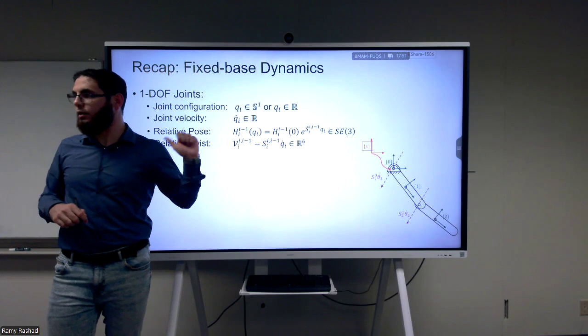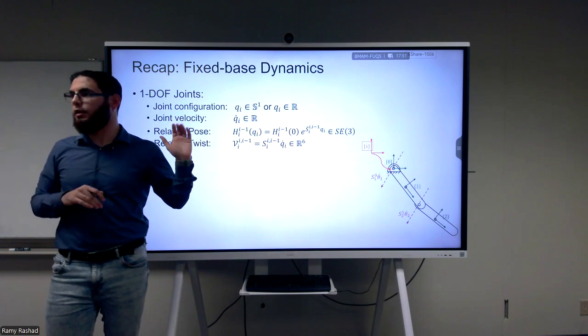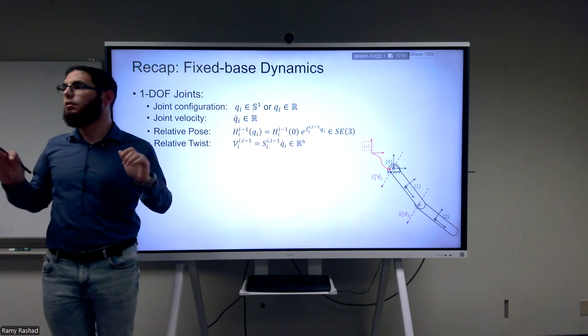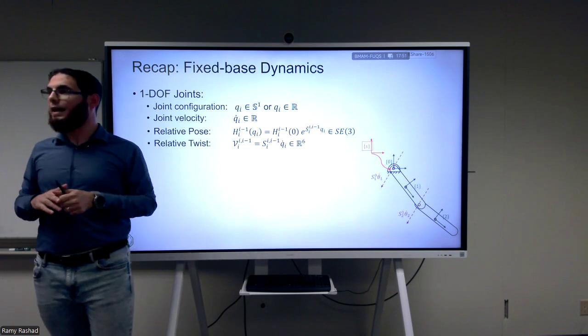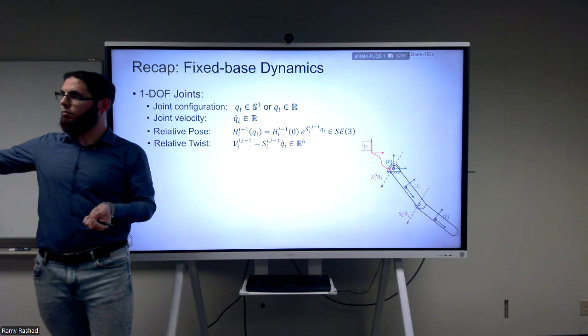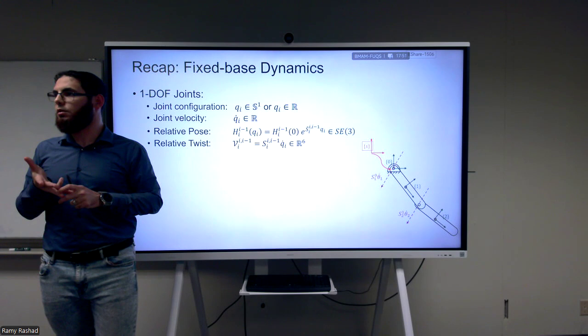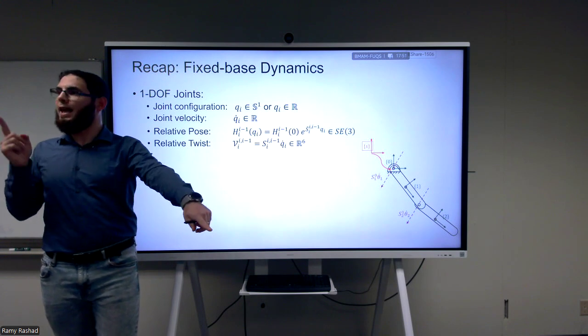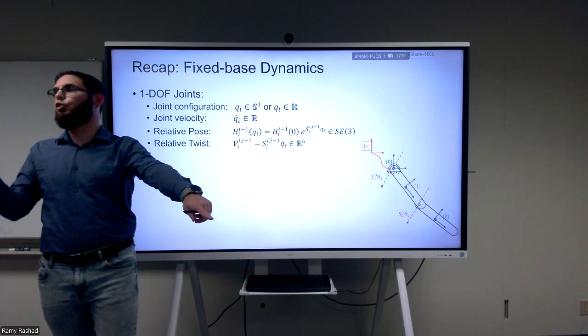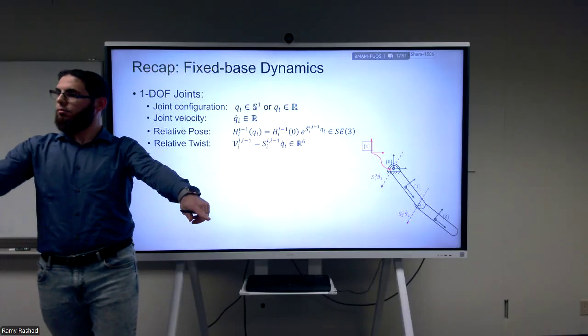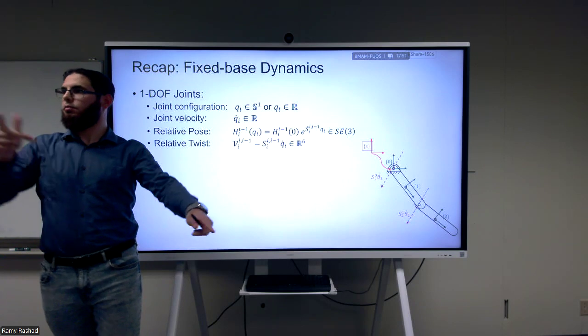I'm going to write it down. This is just an introduction. Planar should have 3. Exactly. You have 6 degrees of freedom in general between B and S, 3 rotations and 3 translations. The planar joint is allowing 1 rotation and 2 translations. So this rotation, this translation, and this translation.